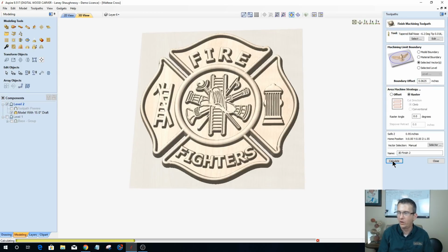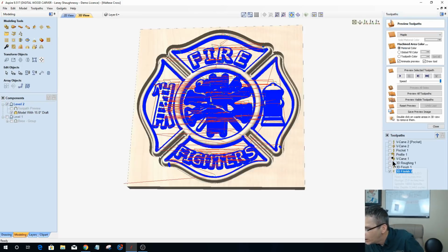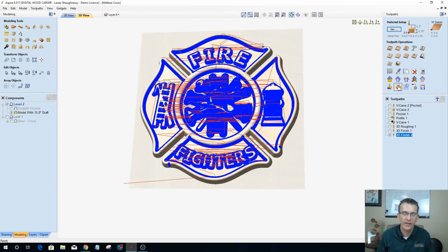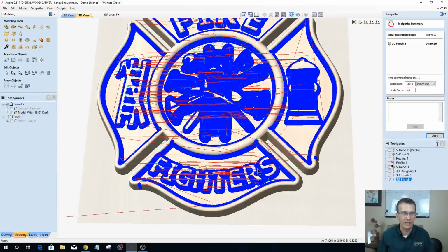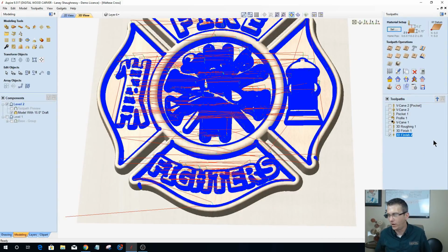But yeah, conical ball nose and tapered ball nose, Jim, same thing. And in my case, I'm talking about a 32nd inch, tapered or conical ball nose, 16th inch, 8th inch, so on and so forth. Great question. All right, so let's look at the time on that with those adjustments to the tool path. 4 hours. So I took off 8 hours just by adjusting my tool path a bit. And I'm still going to get a lot of cleaning up results and everything. So I went from 12 to 4. You know what I mean?